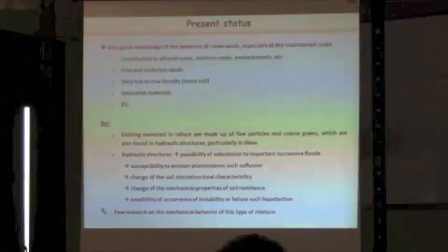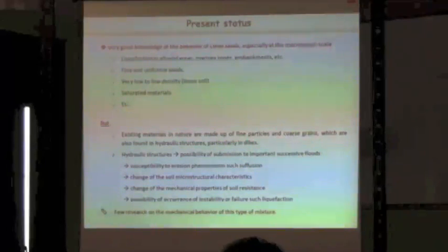This process is called suffusion. When this process occurs, the change of the soil microstructure leads to a change of the mechanical properties of soil resistance. Then the hydraulic structure could fail by the liquefaction process.